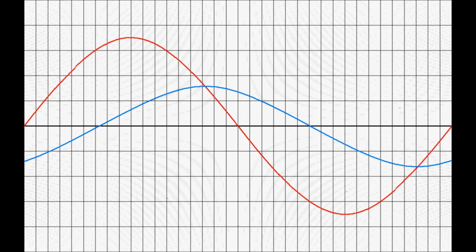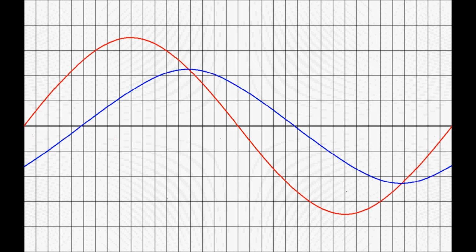However, that sine wave is delayed compared to the source voltage. This delay time depends on the resistor-capacitor combination. Remember that we measure the points in a cycle of a wave in degrees, a complete cycle being 360 degrees. The delay in the peak of the capacitor voltage is a certain number of degrees after the peak of the source voltage. Let's go back to our circuit with our 30 ohm resistor and our 100 microfarad capacitor. At a frequency of 60 Hertz, we see that the capacitor voltage lags behind the source voltage by approximately 49 degrees. Remember that number. We will run into it later.